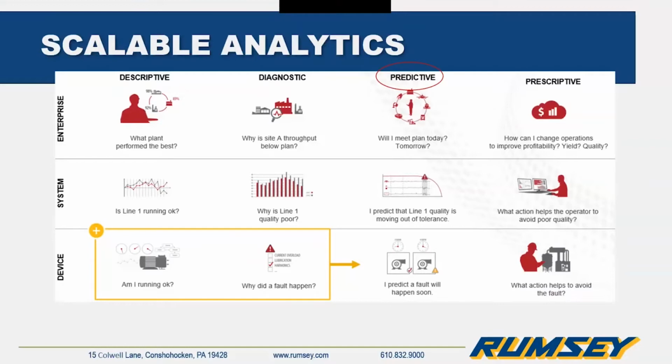And then lastly, we have prescriptive analytics. This not only predicts when something's going to happen, but will also provide a solution. So an example there would be the drive's current is very high. Let's check the conveyor for any potential jam indicators or incoming drive parameters to make sure they're within tolerance levels so the drive doesn't fault in the first place.